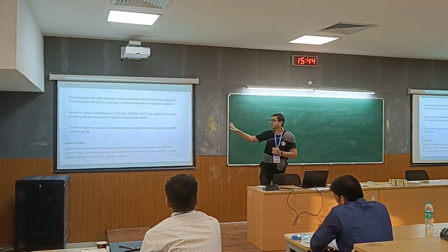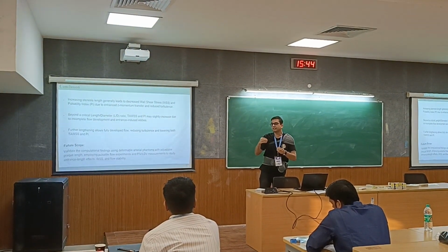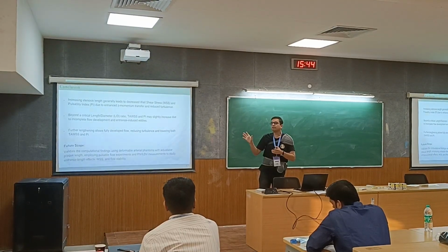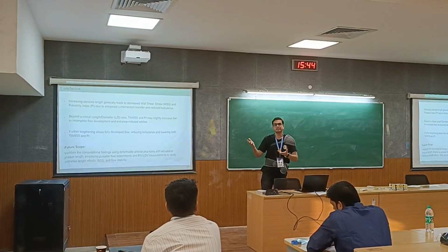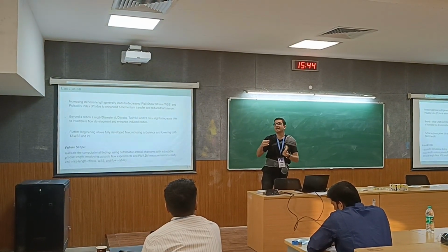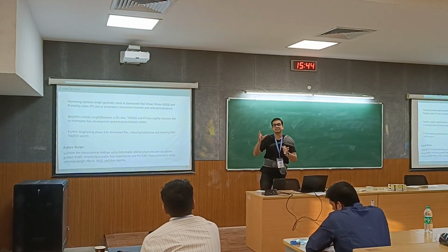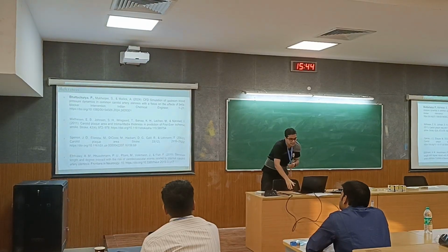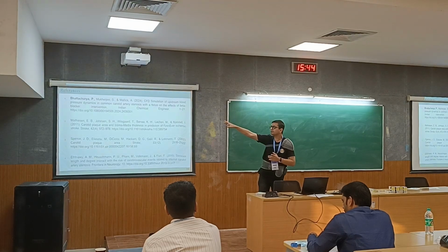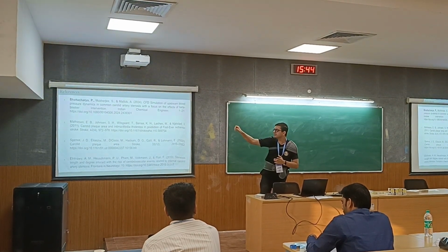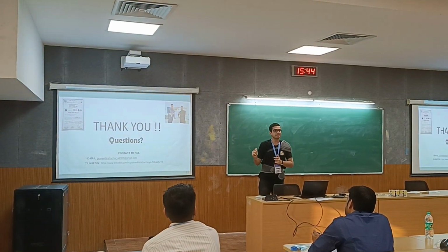So in conclusion, we see that beyond the critical length to diameter ratio, the flow encounters an entrance length effect. Future scope involves people who are working in microfluidics making deformable channels, and thereby we can use PIV and other methods to validate this kind of digital twin. So with that, these are the references. The details of the study can be found in another paper of mine which deals with the blood pressure analysis. And so thank you. If there are any questions, I can take them up.